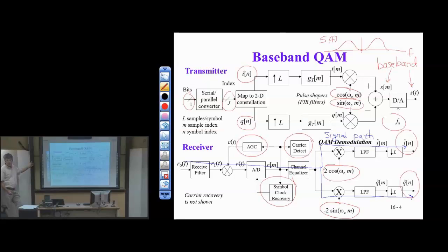Now, there's a lot of intellectual property here. So if you look at where are the patents, where's the market, where's the differentiation in one product versus another, what makes a company have success with their technology on the technical side, it's in these blocks. So it's in the receiver design. Synchronization is a big one. Equalization is a big one. It does depend on the standard, certainly, which of these blocks plays a big role. But automatic gain control is also another one. These, and carrier frequency estimation and phase lock loops, all have a lot of patents that go with them. So this is where the intellectual property is.